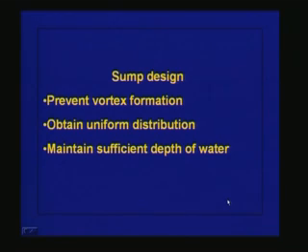Then the other important consideration is the sump design. Whenever we are designing, the sumps should be designed in such a manner that it prevents vortex formation. If vortex gets formed in the sumps, then that vortex can entrain air. Not only that, the turbulence or the disturbance that is created can have significant effect on the pump operation or the flow structure within the pump, and that affects the efficiency of the pump.